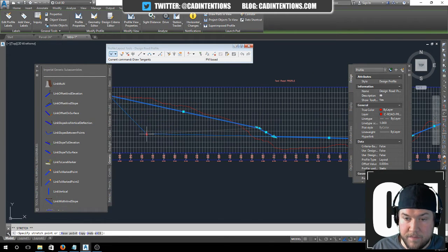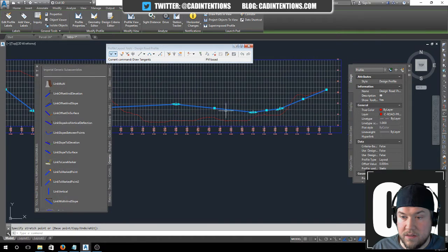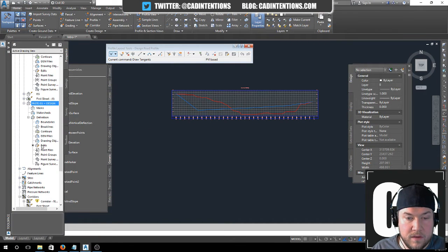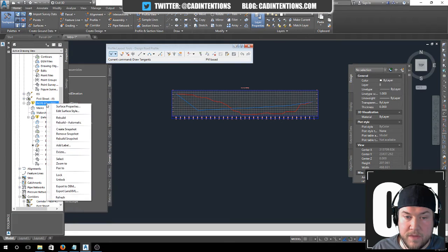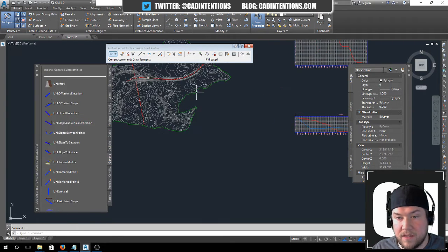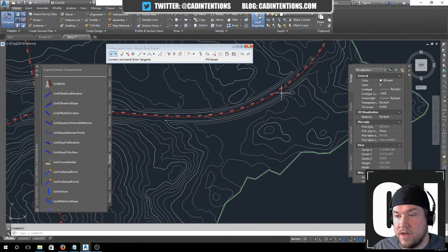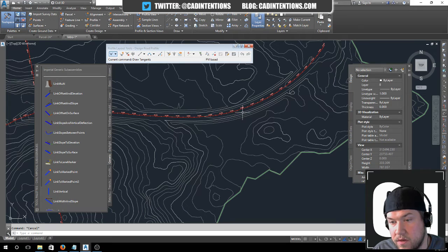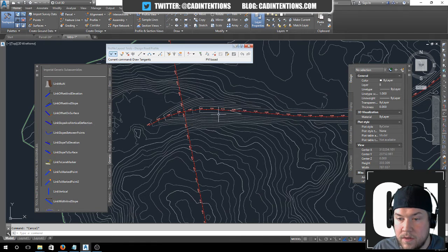Let's say we dig down, we cut through all of this hill here, just consistently rise till the end. You'll really notice the difference on this one. So we just need to rebuild our corridor and update the finished surface that we got pasted over here. Now you can really see in the contours how much it's cutting into the hill, and then over here you can see how much is built up. These are 1 meter contours, so you can see it's built up 1, 2, 3, 4 meters here, and you can see that it's cutting down into the hill quite a bit.